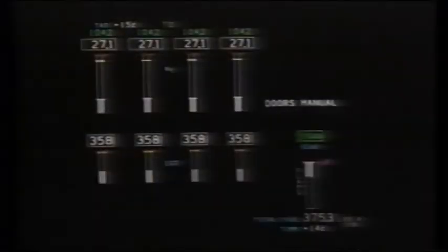Mounted through the rear spar in the number 1 main tank is the fuel temperature bulb. It supplies an input to the fuel system ICAS interface card. Total fuel quantity and temperature shows on the main ICAS primary format. Total fuel quantity can be shown in pounds or kilograms.